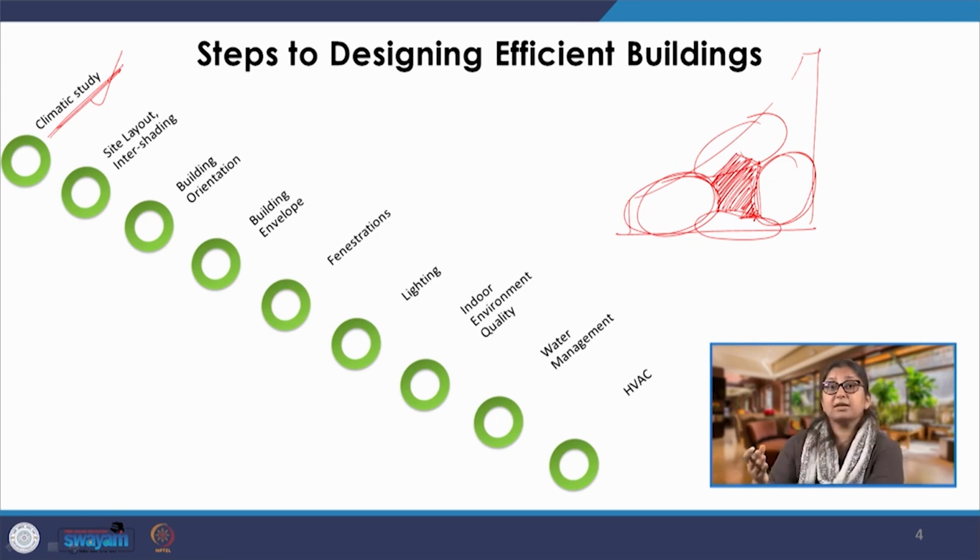And if you look at the traditional buildings which are there, if you look at the classic examples, we will see that difference being evidently clear. We have a different type of building for hot dry, we have a different type of building in warm humid. If you go to Kerala, you will find that the buildings have ample opportunity for air to be ventilated in, huge windows, verandas which cut off the rain but allow the wind to move through in the spaces, and the buildings remain absolutely comfortable, narrow courtyards which allow ventilation to happen throughout the day and night.